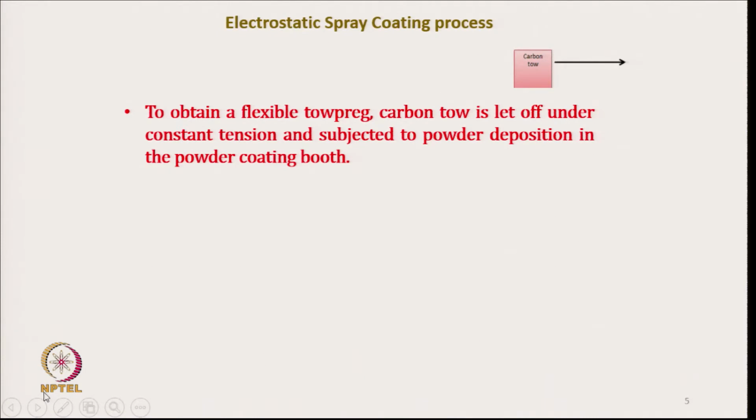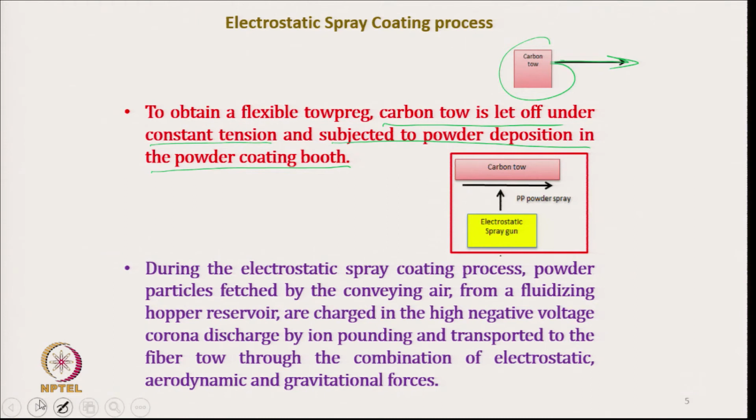So, to obtain a flexible tow preg, carbon tow is let off. So, this is the carbon tow, let off under constant tension. So, constant tension is important, and it is subjected to powder deposition in the powder coating. So, carbon tow is delivered here.